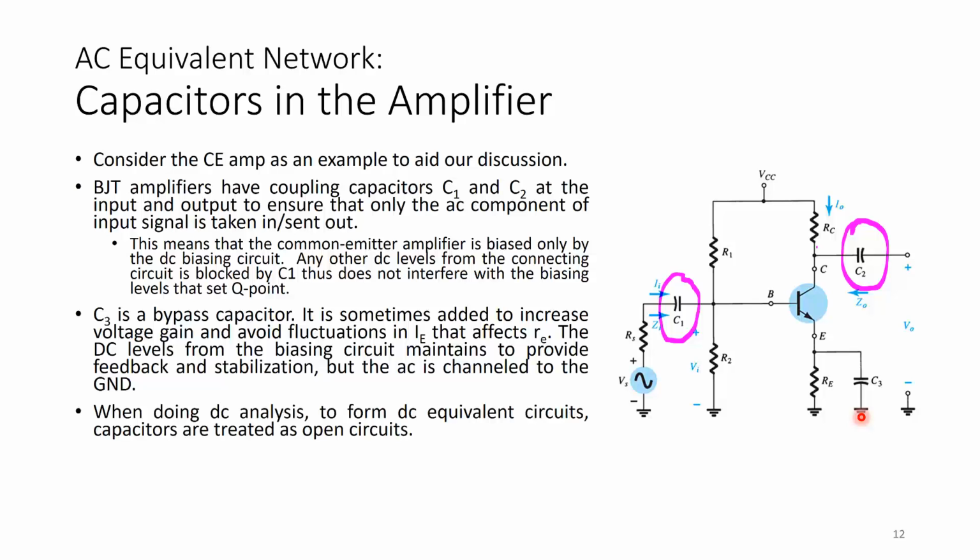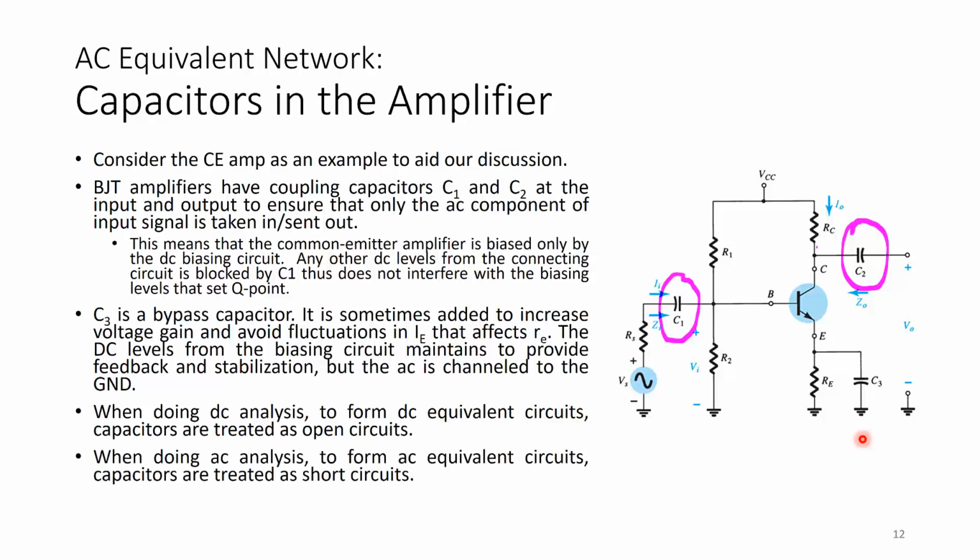When doing DC analysis to form DC equivalent circuits, because capacitors are reactive devices, the capacitors are treated as open circuits. But for our AC analysis, to form AC equivalent circuits, because now it becomes very low impedance with the AC, capacitors are treated as short circuits.